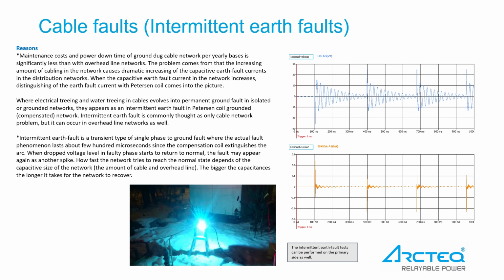In larger networks in amperes, a less frequent strike-through can be expected. The following can be presented as a rule of thumb: in small or medium-sized networks, less than 60 amps, approximately a 250 to 350 millisecond strike-through interval, and in large networks, roughly 100 amps or more, approximately a 500 millisecond strike-through interval is expected.